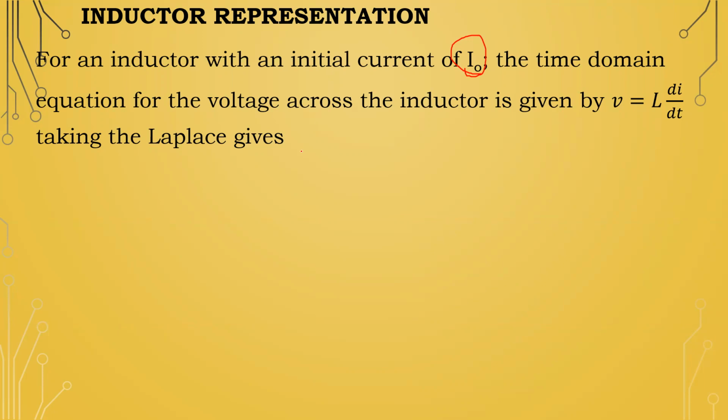And going back to the definition of Laplace, which is the integral from 0 to infinity of f of t e to the minus st dt, if you were to do that for this function, then V would be equal to L into sI minus I at 0 minus. And of course, I at 0 minus we know is equal to I0.